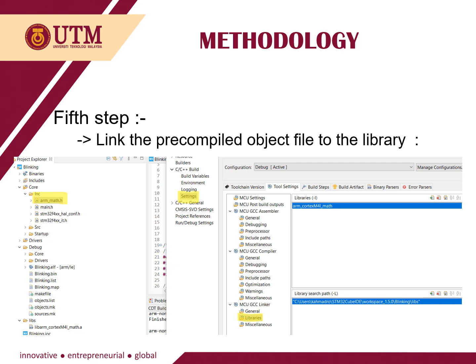Then on the top, in the Libraries part, click edit and type in arm_cortexM4l_math. From there you can recompile your code with the define and the arm_math.h, and you will see that it compiles clean. There will be no errors.